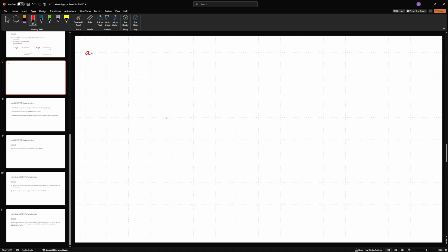Now for a PN junction, we know that the Fermi levels have to be aligned. In this case, the quasi Fermi levels are aligned. So let me draw that as a reference line, and let me say this is EF for the device, and since the P side is here, then my valence band is going to be up here. Let us say this region I'm leaving for the junction. Since this is the N side, the conduction band is going to be here. Conduction band is going to be all the way up here. Valence band on this side is going to be here. And I will just connect the two. So this is a PN junction, EC and EV. So this is the band diagram for a PN junction.